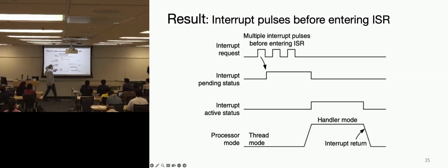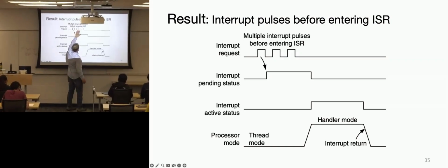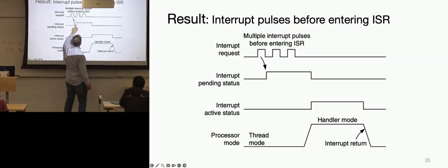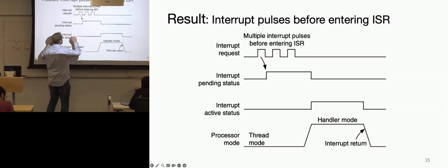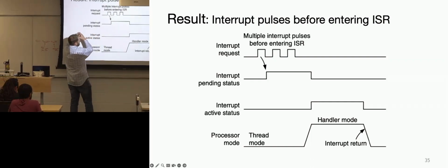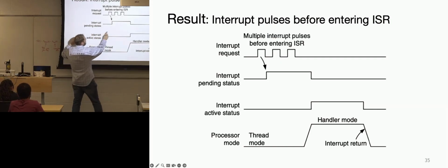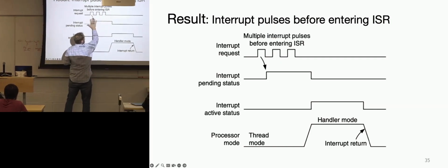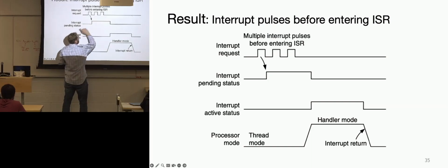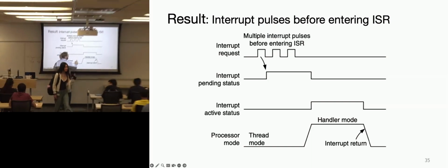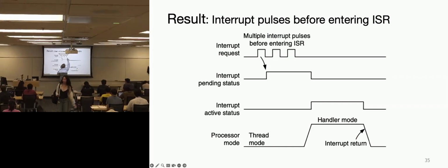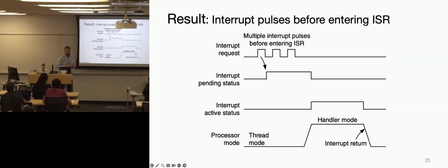And so here, remember, this line is just a register where each interrupt has one D flip-flop or one state holding device in it. So it's one-hot encoding, where each individual location denotes which interrupt it is, and so there's not enough information to hold, hey, I got 3 pending interrupts. This only says I have a pending interrupt, then it went into active, then you went back. You don't do it 3 times, because there's no way to hold that state information.